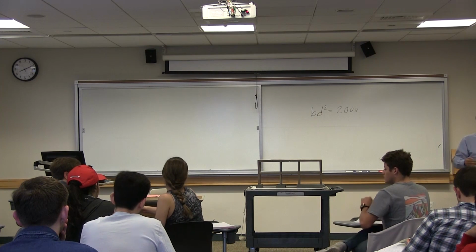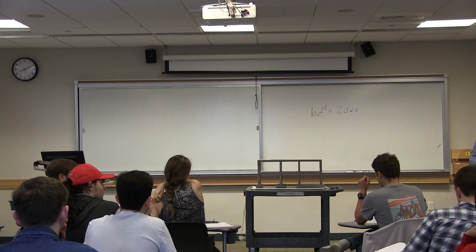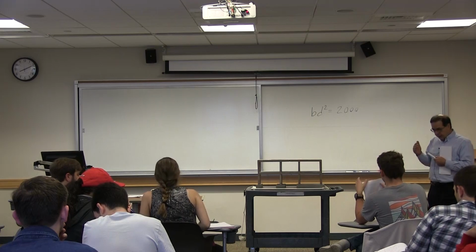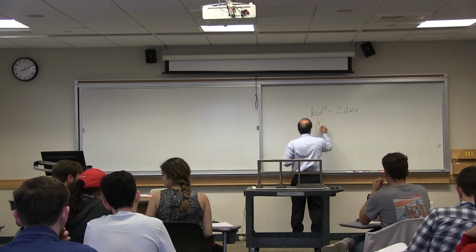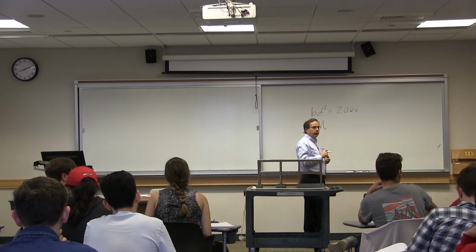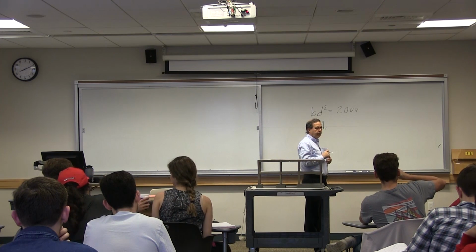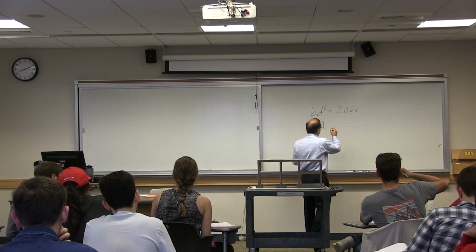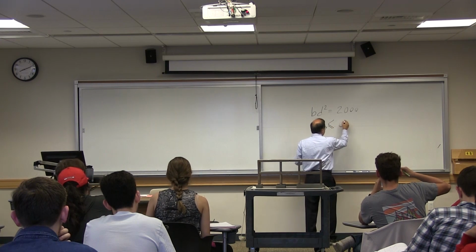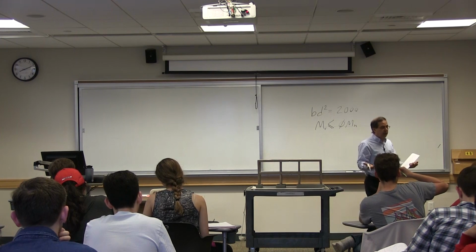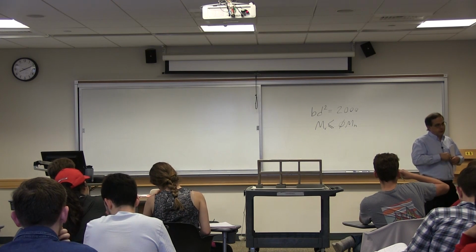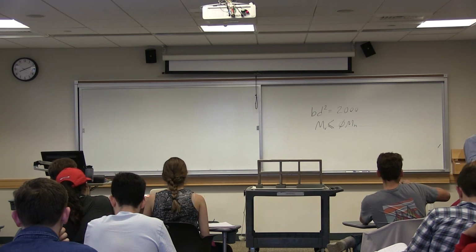Okay, let's start all over. The original ultimate moment, Mu, is less than the safety reduction factor times the nominal moment, phi Mn. Those terms should be very specific. That is the way you design. In other words, you set them equal and you calculate.